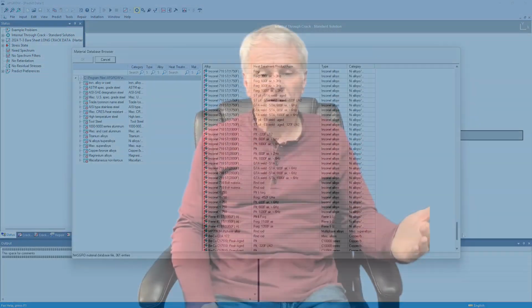Then if we wanted to look at what you use, you can completely control that. If you think for your case the Foreman is better, you can use the Foreman equation. If you think the Walker is better, use whatever you want. I always recommend Tabular Lookup, but it all depends. You might find that we don't have a material in Tabular Lookup that you want. You might decide, well, I'll use the NASGRO version 3. Just be aware there could be issues with it, but that's all I'll say about it.